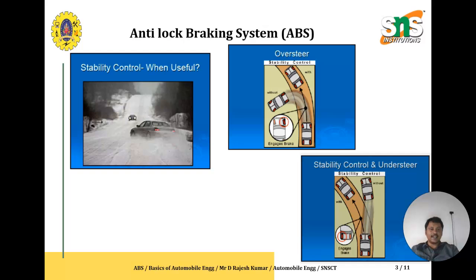And you can see on the right hand side of the images the oversteer and understeer concept. The vehicle is subjected to turn, but the vehicle turns in advance. That concept is oversteer, because of the steering response. As well, you can see the understeer also. It is supposed to travel on that orange colored path, but the vehicle goes out of the path, out of the inner radius. So that is also because of the steering rate with respect to the vehicle speed.